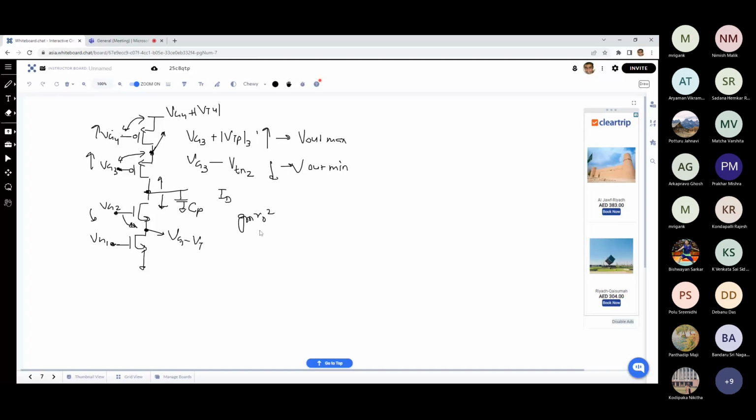R down is also the same. So basically gm ro square by 2. So the net small signal resistance between this point and AC ground is gm ro square by 2, which is a large value. As compared to ro, it has a big multiplication factor. This is a very high impedance node. So if your parasitic capacitance is increased, the circuit will become slow and bandwidth will get limited. So there is a conflict between, of course, the swing and the bandwidth.